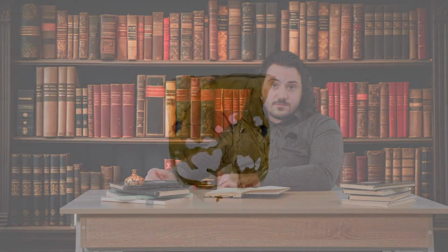With that being said, let's explore some problems of the technology. Since LiDARs emit rays of light, if we are to try to scan something that reflects light or lets it pass through, we run into some problems. For example, as you can see, this scan has multiple holes due to the fact that light passes through the glass. That's used for the restoration of the item, but the old Roman glass has enough impurities to allow the scan to work.